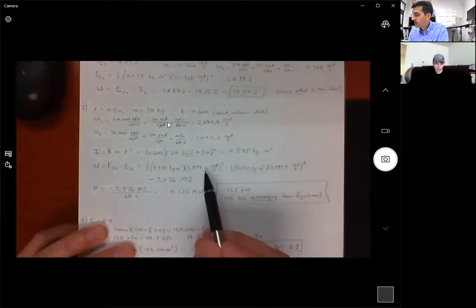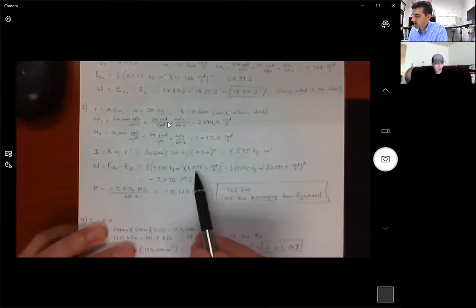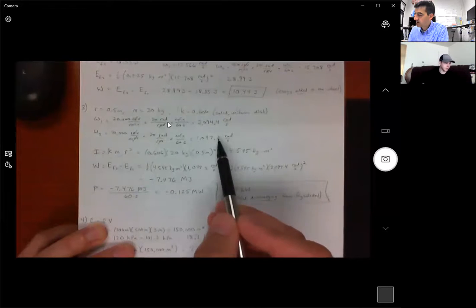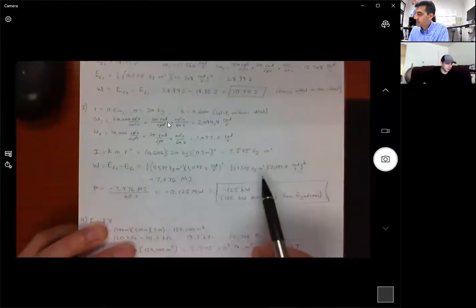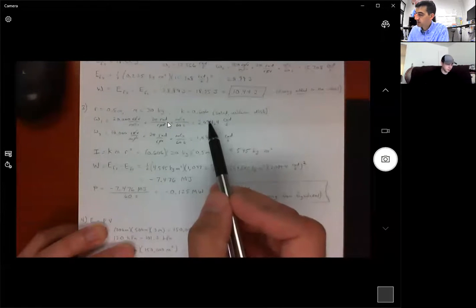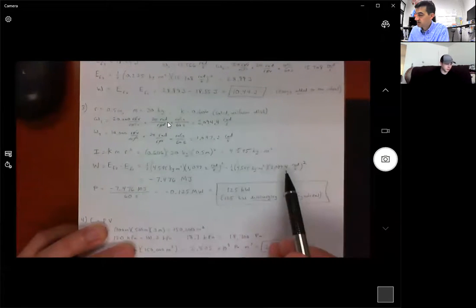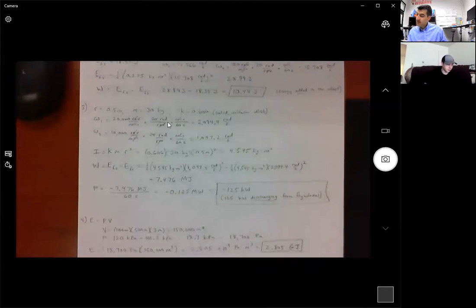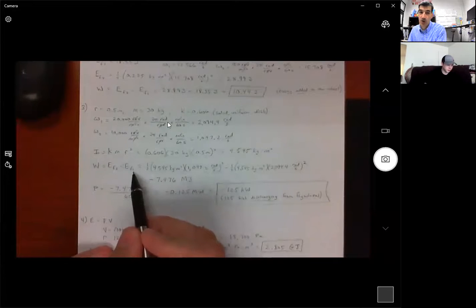And we have our angular velocity. So this is our angular velocity from our calculation at time 2. This number goes to here. And this is our angular velocity at time 1. So this number comes from here down to here. So after that, we're just going to subtract. Obviously, we know our flywheel is rotating faster at time 1. So when we subtract time 1, we know we're going to get a negative number here.